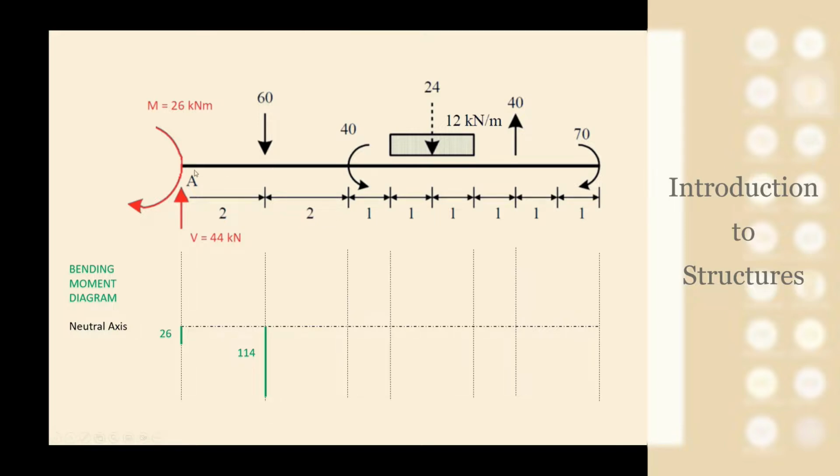In between forces, for the bending moment diagram, the variation is not constant because this is not a shear force diagram. The variation is linear. You can take this as a rule, but you can prove that this is right by calculating the value of the moment at any cross section in between A and 60 kilonewtons, and you will see that this is a linear equation.